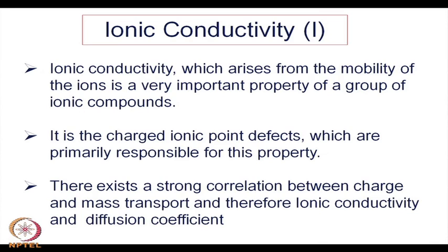So, that really completes our discussion on the semiconductivity in oxides, how it is determined by the partial pressure, how it is determined by the impurity content, and to what extent it is determined by the temperature, and all these things can be explained once we understand the band diagram of the semiconducting or the insulating oxides.